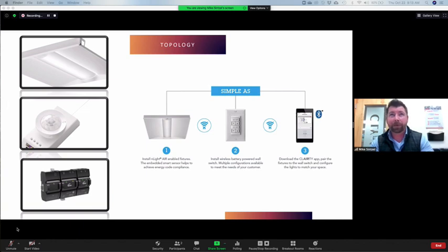These embedded components have digital dimming, occupancy sensing, detection utilizing PIR, microphonics, daylight harvesting, usually with a built-in photocell. So that one center left there, that is a dual tech. So there's microphonics, there's photocell, there's PIR, everything in that little tiny sensor, and it would go into mostly every fixture.